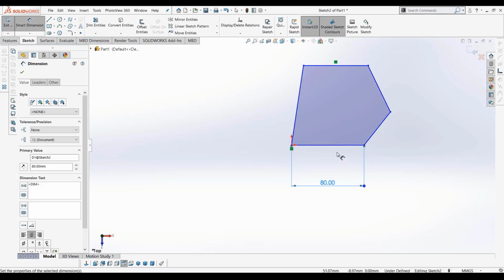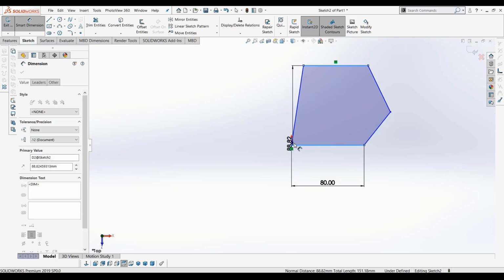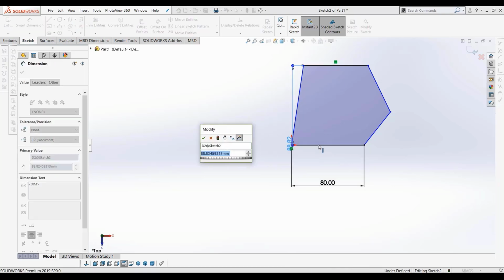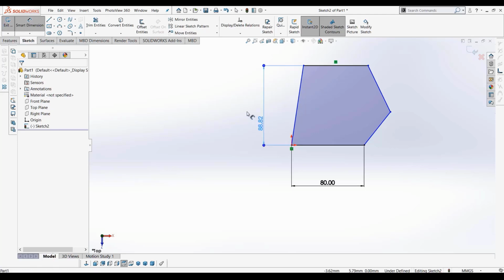The reason I say to move the mouse to an empty space and click is that, for example, if I say the distance from this to this, and I click in a crowded area like here, it might snap to another element behind it, causing issues with your click. Of course, there is no problem here right now, but to prevent this situation from happening, I recommend that you always click in an empty space.